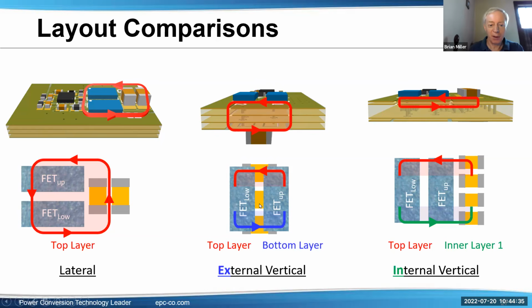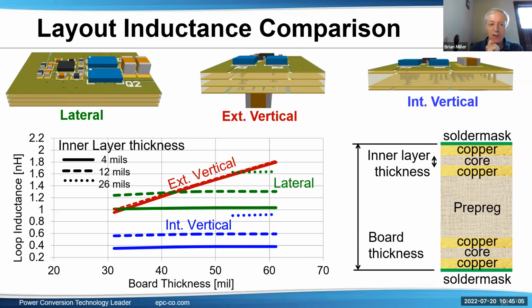having the switch node, which is between the FETs, coming right out. Yes, I think it does work. We did find it works better to have the switch node there, because even with the ground, the capacitance didn't seem to affect it as much. Okay. Seems like the inductance is more of an issue, and some of the losses we saw versus the other one.